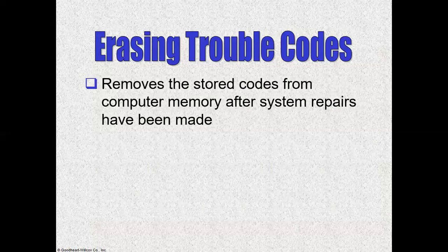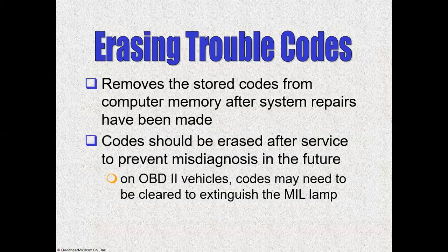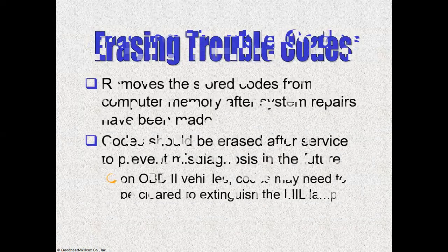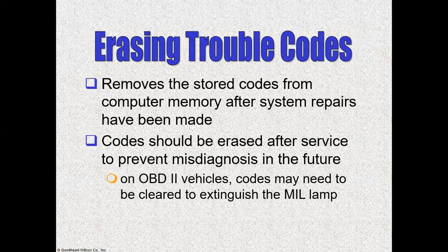So, erasing trouble codes: remove the stored code from the computer memory after system repairs have been made. Codes should be erased after service to prevent misdiagnosis in the future.